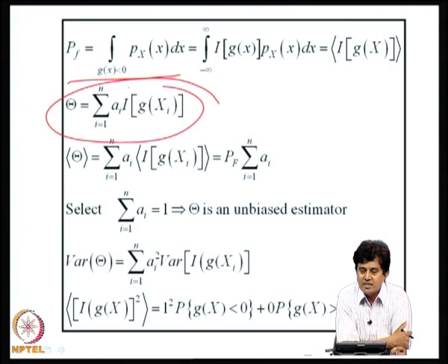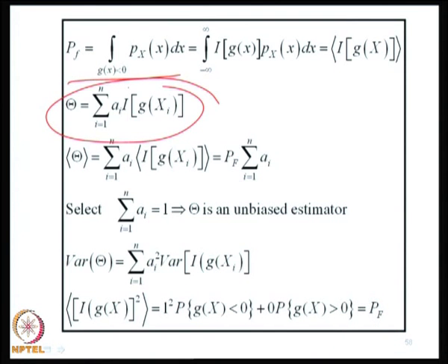This question is of considerable significance when we analyze the response, because if you are applying simulation methods for practical structures, and one run of computer simulation of the dynamical behavior of the system takes about, say, 5 minutes of CPU, and you are evaluating a probability of failure of the order of 10 to the power of minus 5 with a coefficient of variation of, say, 0.01 as I was mentioning, you will need to run the computer code 10 to the power of 9 times.